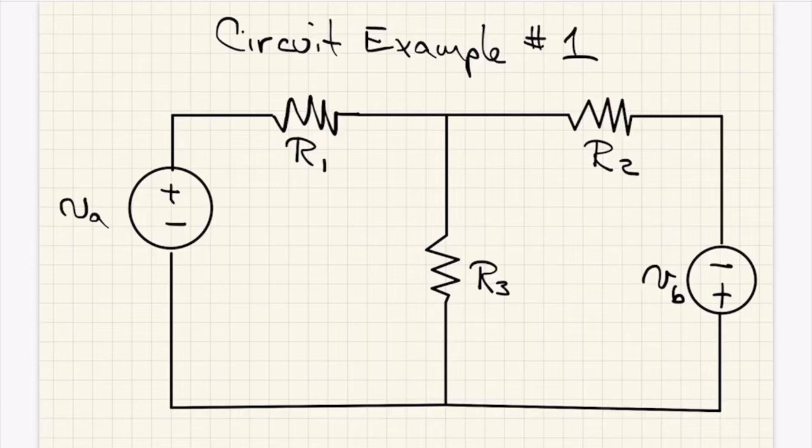So the first thing, once we've got the diagram figured out, is to label the currents and then the resulting voltage polarities. Really, we don't know the voltages yet, but we know which is going to be plus and which is going to be minus. It's traditional to take the resistance R1 and say the current that is going to flow through that, I'm going to call I1.